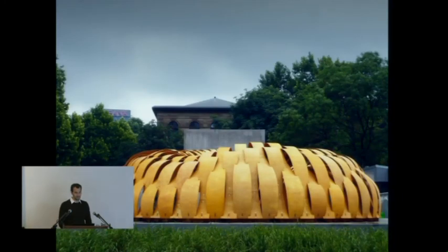So this super thin skin is at the same time the load-bearing structure, which also needed to actually fulfill the stringent regulations of a German building application, which we always need for these prototypical buildings. So we have to go through the whole process of validating that it is structurally stable in regards to wind loads, snow loads, and it fulfills all requirements of a building regulation.